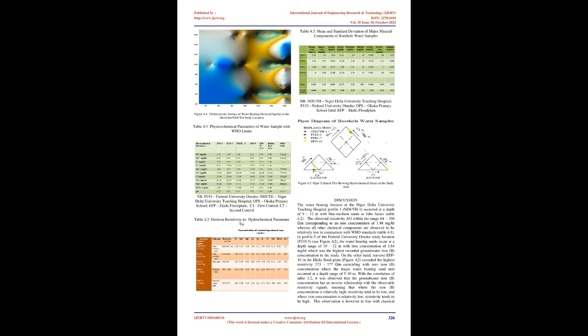At the aquifer level, zones of uniform electrical resistivity with wide lateral extent of sand body were noted and picked as horizons of interest. The drilling points were carefully selected at locations where these extensive sand bodies characterized by uniform electrical resistivity contours bulge closer to the surface with a view to minimize drilling costs. Apparent resistivity logs were also extracted from 2D profiles to show the electrical resistivity variation with depth and perhaps to provide pre-information on what should be expected from the drilling.